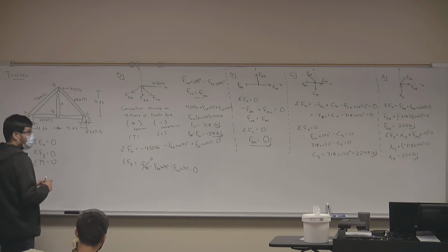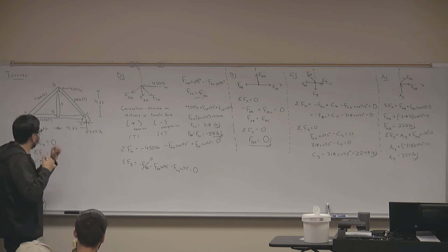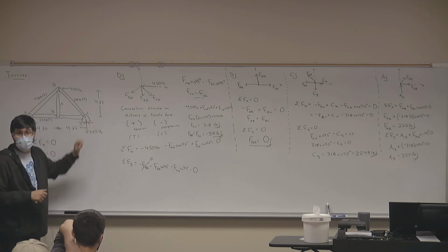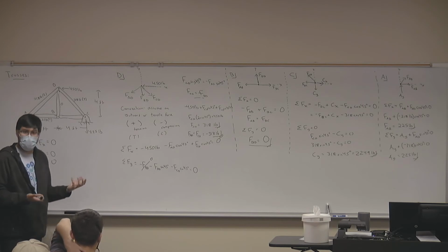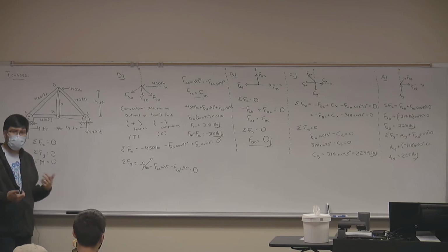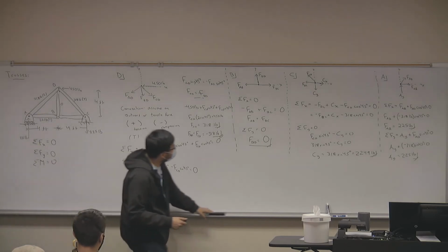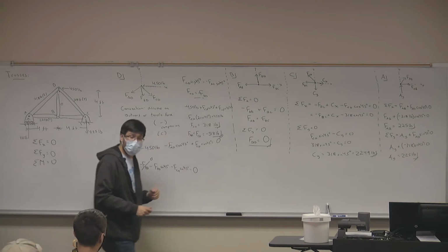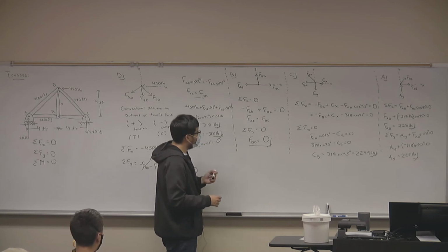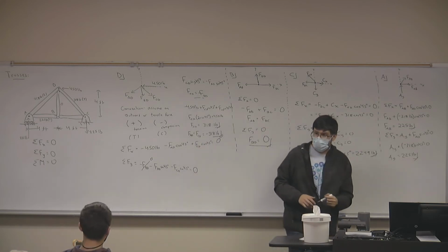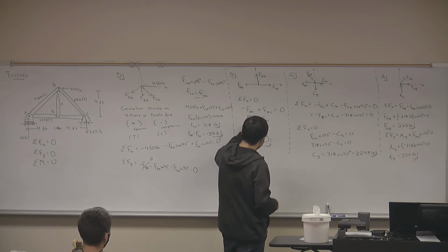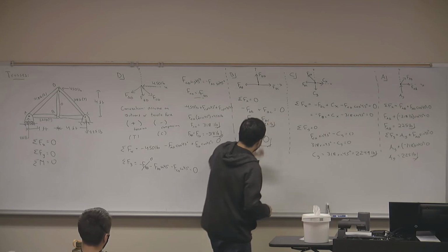Ooh, it looks like we're starting to solve our system. I think it's starting to all make sense. We have one truss left, and then we have one X reaction left. So do you think we have everything we need to solve this? Okay, so what's the next logical step? Where do we move back to? Take it back to B. Exactly. We go to B. Why? Because we already have this relationship. FAB equals FBC. We already found that FAB is 225 pounds, right? So what is FBC equal to? 225 pounds. And is that in tension or compression?